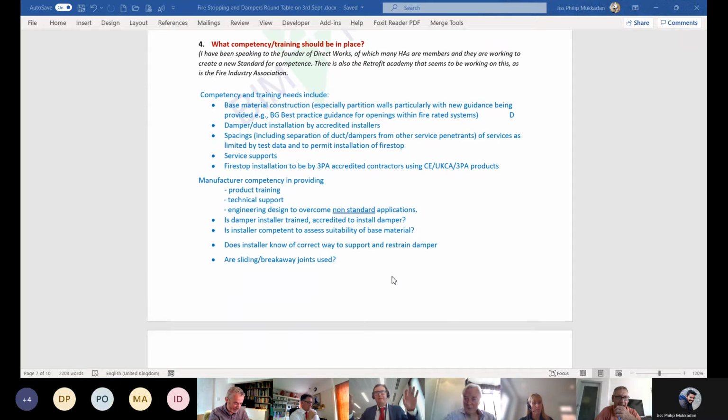If you think of it this way, the building in construction, let's talk about procurement. Generally, we'll hire the building services engineers and the subcontractor to draw it all out before drywall is involved, or before brick and blockwork is involved, or the fire stoppers are even appointed. We have changed that, but a lot of people haven't. So then they're thinking the architect, who has never built a drywall in their life, no disrespect to architects, does not understand everything that Building Regs want, all the different distances between doors and surface penetrations and deflection heads, and can't really draw that. So by the time that dry lining contractor is on board and fire stopping, that horse has well and truly bolted. And therein lies the current problem in the industry.